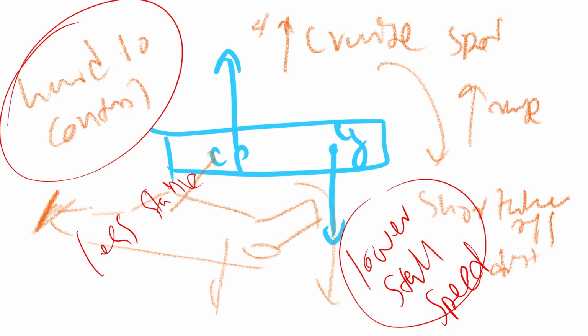So we have to make sure that we do not exceed these limits, because we will have consequences if we do that, right? So we have to always stay within the limit and make sure that the CG is at the front. We have to make sure that the CG is in front of the center of pressure in order for us to have stable flying conditions. Okay, you have to learn these.